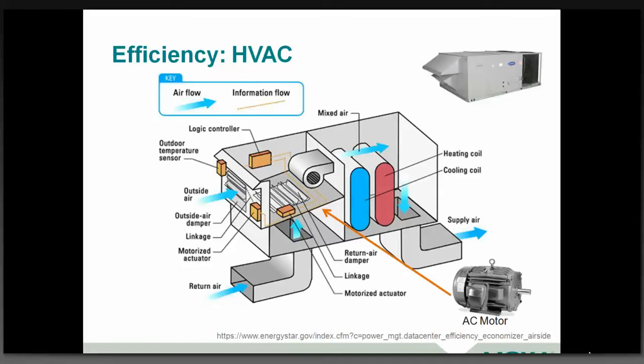A lot of these systems are meant to be on or off and nothing in between. So the ways that they've regulated airflows and temperatures and the like have been by running the system at full blast and opening and closing dampers, or running the systems on and off and cycling them, which doesn't give you good temperature regulation.